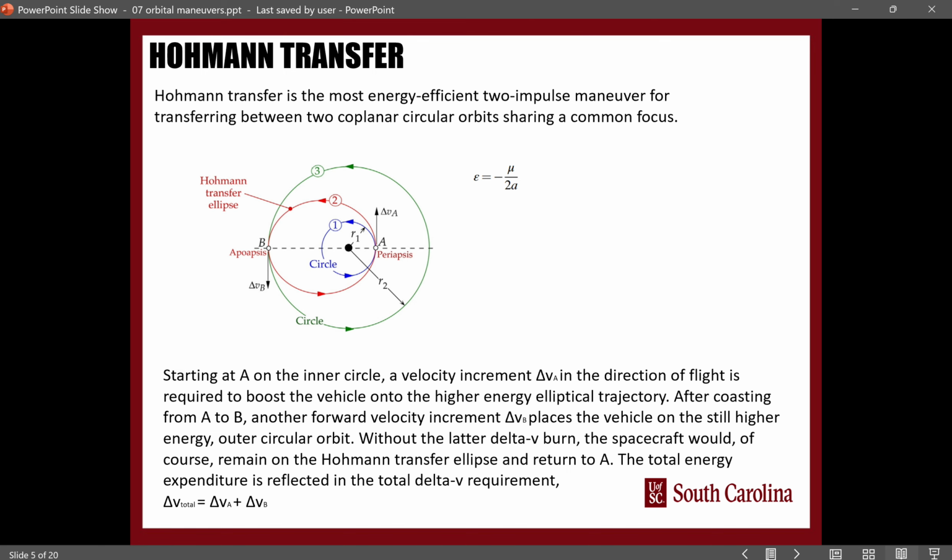But so we are going to start talking about orbit transfers by talking about Hohmann transfers. Hohmann transfers are the most energy efficient transfers that you are going to come across. Why is this the case? Or like, how do Hohmann transfers work? Hohmann transfers go from the periapsis of one orbit to the apoapsis of the other orbit, right?